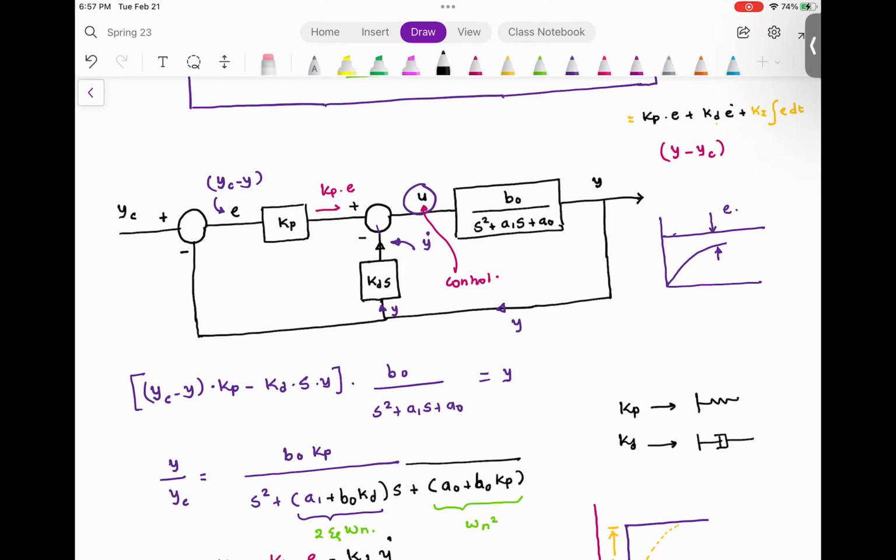And on the microcontroller, you will implement that equation in a for loop. At every iteration of the loop, you will get a certain value of the control input, and that control input will get fed to an amplifier, and that amplifier would exert the amplified effort onto the control circuit. So that is how it will be implemented.